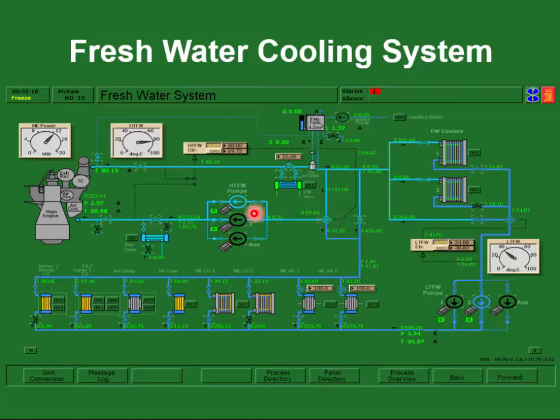If the temperature is low, the flow through the system is through the pumps, into the main engine, out of the main engine, and then the three-way mixing valve is going to just circulate the water in this fashion. If it is trying to bring the temperature down, the three-way valve will shift, and water from the low-temperature freshwater cooling system will flow through the pumps, through the engine, and then it goes back through the cooler and through the system like this. Okay, so this three-way valve is controlling the temperature of the main engine.